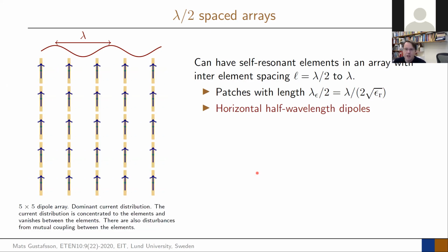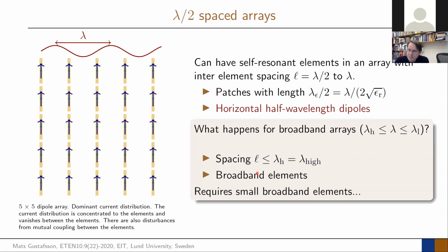And if we do the same here, we can look at the currents, because the current gives the radiation. So it means you have strong currents here, and in between it's equal to 0. So in the gap there is no current. So you have current, no current, current, no current, and so on. But it fits again the sampling of lambda. Because in some ways, it's very strong, it's weak, on the order of lambda or lambda over 2. So the elements here really fit in this lambda over 2.